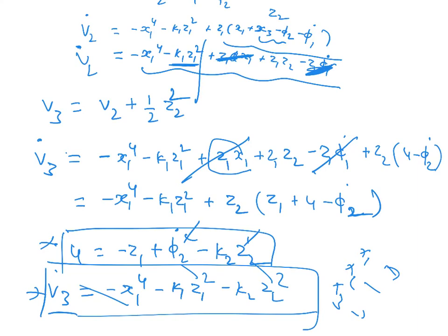Good. Are you guys having some fun? Maybe this sliding mode assignment will give you some simulation fun, and some understanding of the constraints of simulating nonlinear controllers and things like that. So you can always use an S function kind of approach to just simulate x1 dot, x2 dot. And in fact, you don't need a separate controller. You can compute your u right in the S function itself, or you can have a separate u. Doesn't matter. Okay.